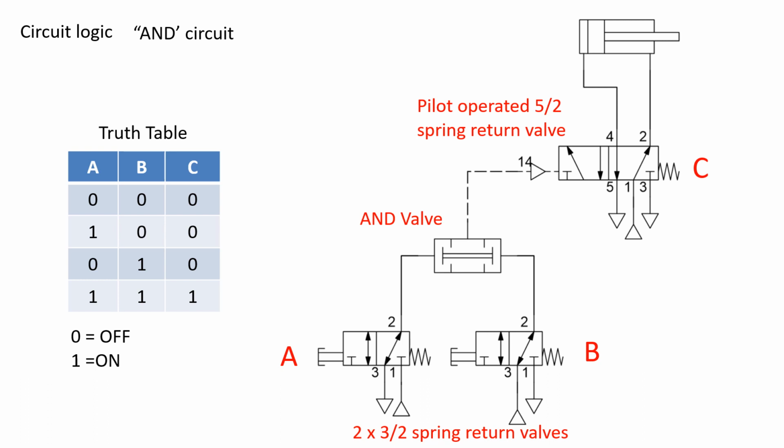I've just completed a risk assessment for our can crusher and realized there's a serious crush or amputation risk associated with using the can crusher. My control measure on my risk assessment will be to add an extra button and force the operator to use two hands, or press two buttons at the same time, to actuate the crusher or the cylinder.